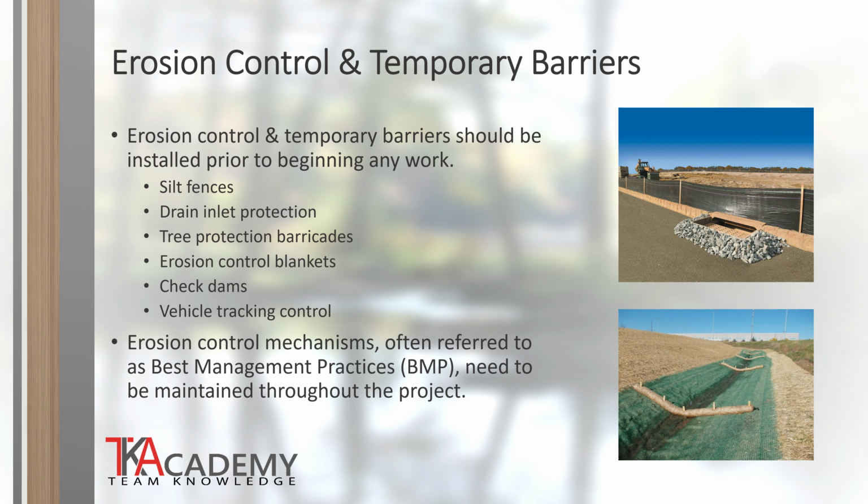Erosion control mechanisms are often referred to as best management practices, or BMPs. These need to be installed, maintained, and inspected on a regular basis throughout the entire construction period. Most jurisdictions will require, on any project sites larger than an acre, that a Storm Water Pollution Prevention Plan, or SWPPP, be developed, submitted, and approved prior to the beginning of construction.